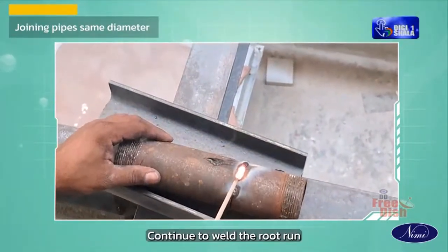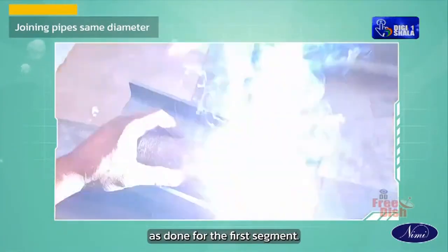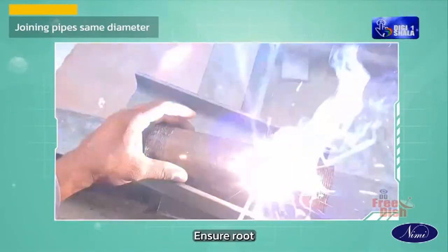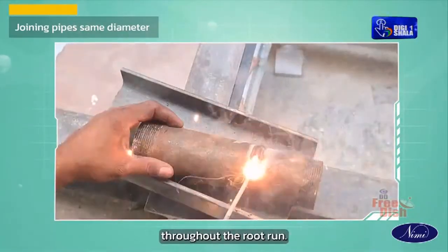Continue to weld the root run for a second quarter segment as done for the first segment. Similarly, complete the root run of the third and fourth segments. Ensure root penetration by maintaining a keyhole at the root throughout the root run.